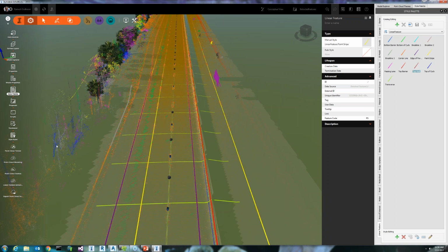Ramesh, when you start a project where you're going to work with point cloud data or feature extraction specifically, do you have to start with a clean model, or can you maybe start with Model Builder to get your bearings? Is there any restriction on that? No, you can use either way. You can use Model Builder and then put your point cloud on top of it and start extracting your features also, or use a clean model like I did here.